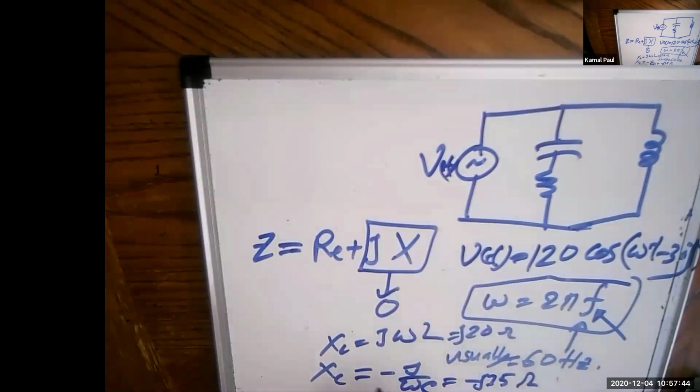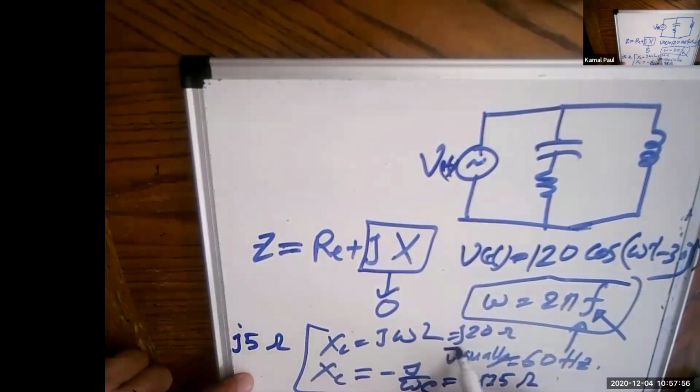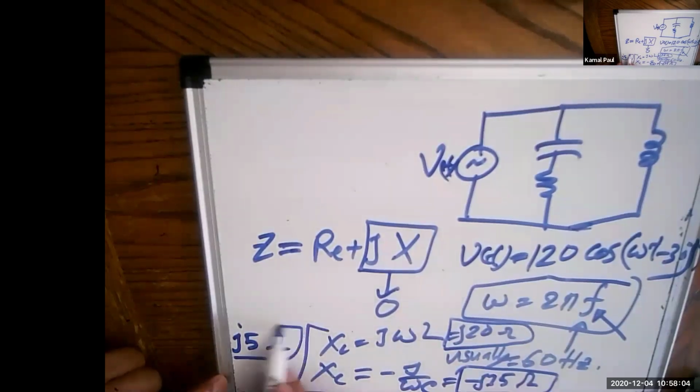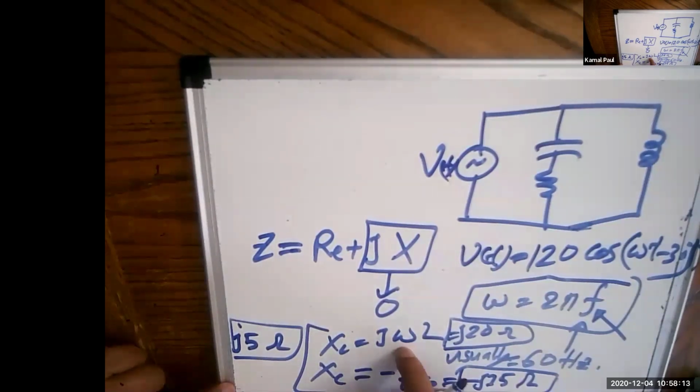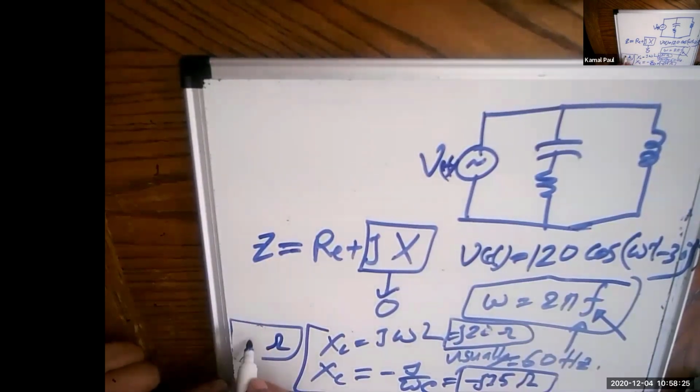5, right? If we add these two in series, the resultant will be 5 ohm. So what do you see from here? The inductor is giving positive reactance and the capacitor is consuming that reactance, so the resultant is now 5. Now we can increase or decrease this capacitor. We can modify this capacitance value, or we can change the angular frequency omega so that these two quantities will be equal. Whenever they are equal, the imaginary part will be 0 ohm.